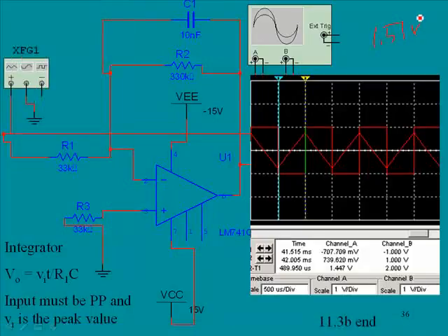So what that's saying is that during this positive cycle, there's going to be a current through this device that's going to charge this capacitor, and it's going to develop a voltage. Now, during this time, you'll notice the voltage appears to be going negative. Well, the reason it's going negative is because it's fed into the inverting side, so as this is positive, the output's going negative, which you would expect. And as the peak voltage goes negative, you see the charging of that cap going positive.